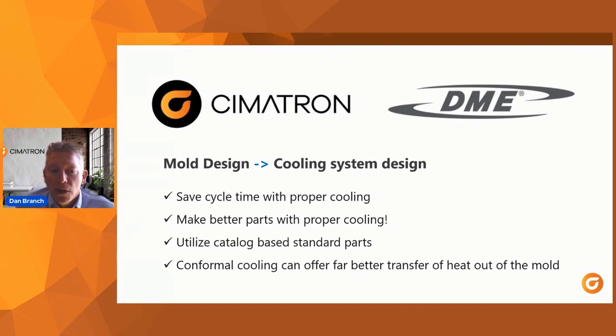And it's probably going to mean a better quality molded part too. Cooling system design needs to be well thought out, but it should be easy to manage, and it also needs to rely on those standard components that are going to work with the press and the facility. Any opportunity to incorporate some conformal cooling should be considered whenever possible.